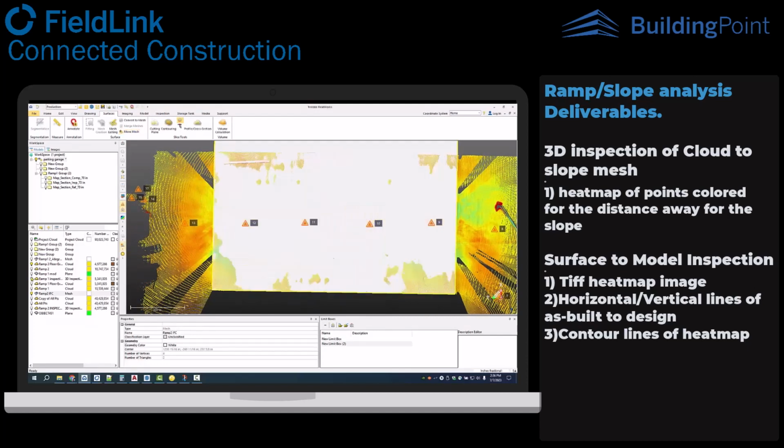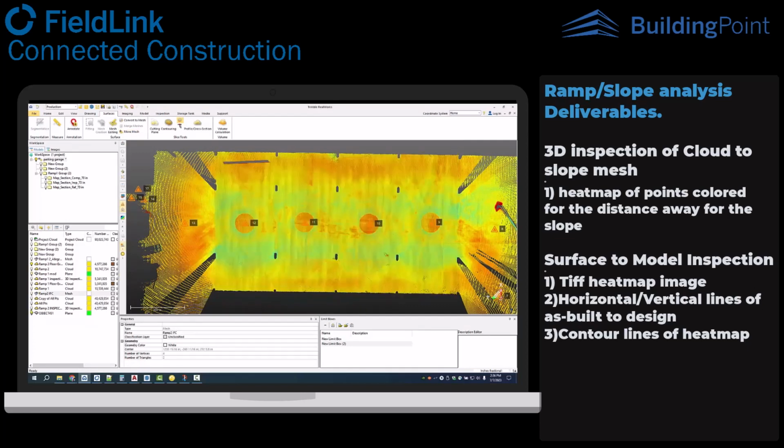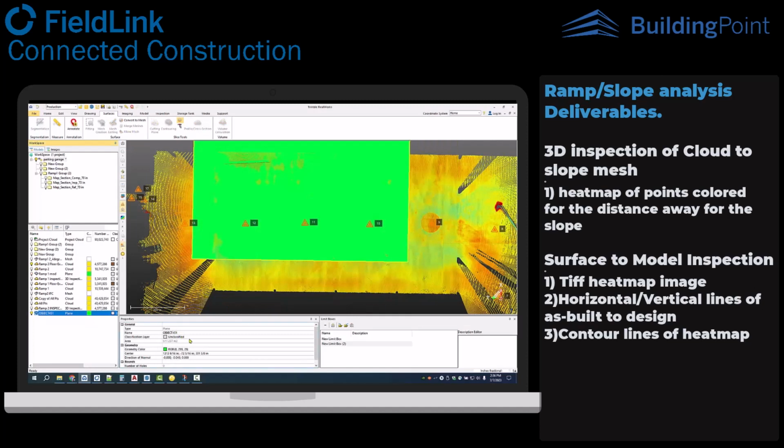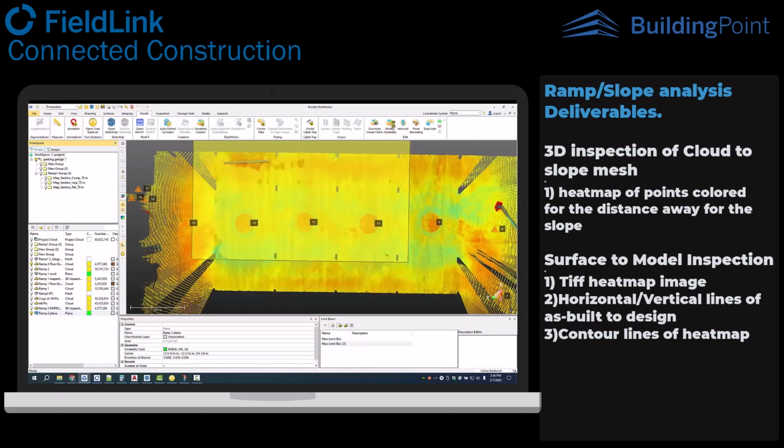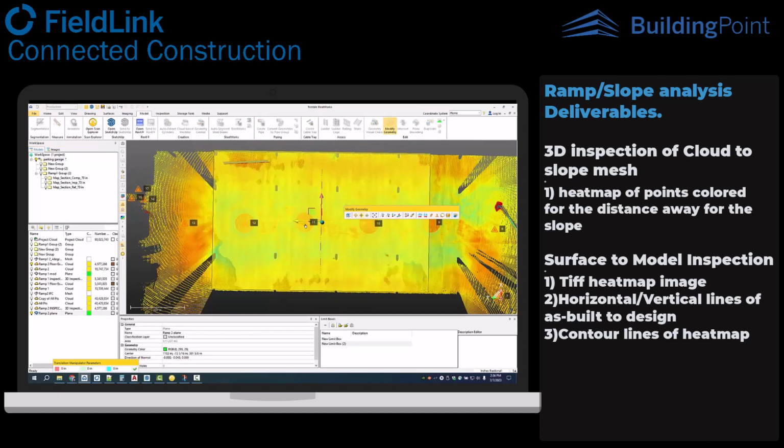The other way, and why I showed you that, is so I can show you this as well. I'll come back down here to ramp 2 from this plane that I created. I can move this the same way, but it's actually going to be a different movement. So I'm going to go back to model and go to modify geometry. Again, this slope is already set and the elevation should be good, but we'll see that here in a second.